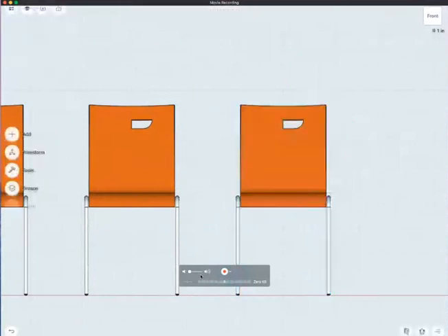Another nice feature of direct modeling is also the self-healing or self-repairing. Essentially, when I move these faces or I adjust a fillet or remove the fillet, the software behind the interface that deals with the geometry, for example, retrims and repositions everything.